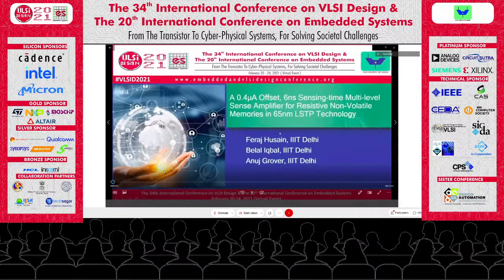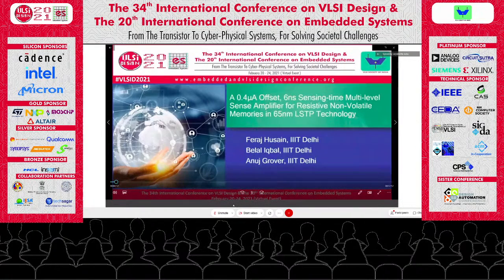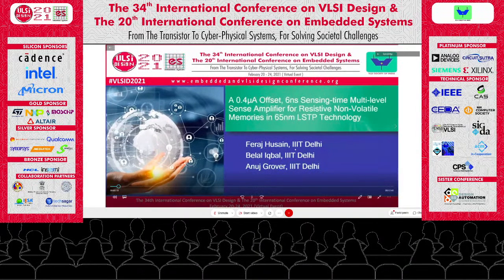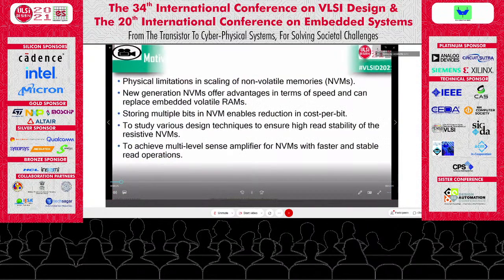Good morning, everyone. I am Firaz Hussain. It is my honor to present my research work in the 34th International Conference on VLSI Design. My topic of presentation is 0.4 microampere offset, 6 nanosecond sensing time, multi-level sense amplifier for resistive non-volatile memories in 65 nanometer LSTP technology. Authored by Firaz Hussain, Bilal Iqbal, and Dr. Anuj Grover.